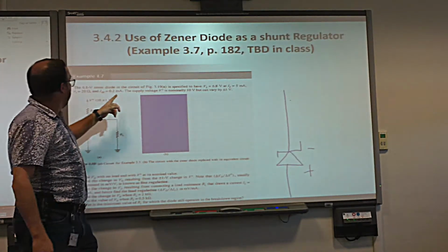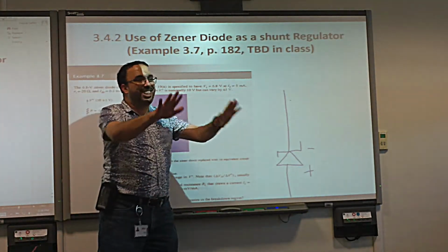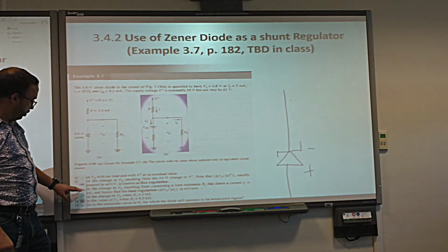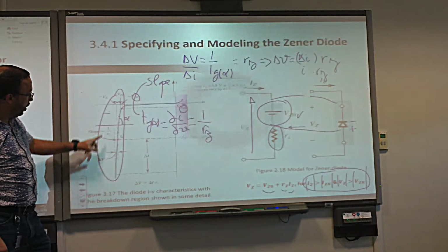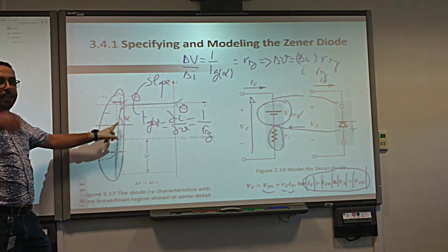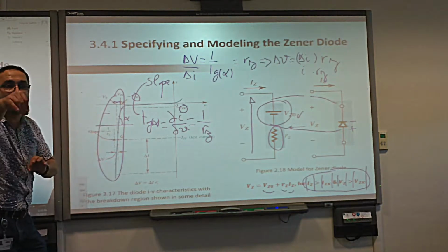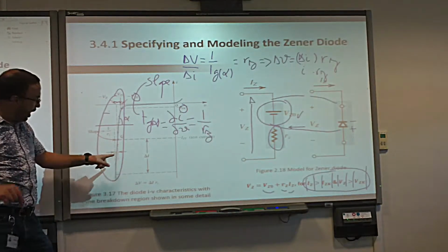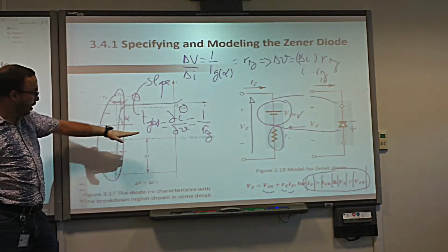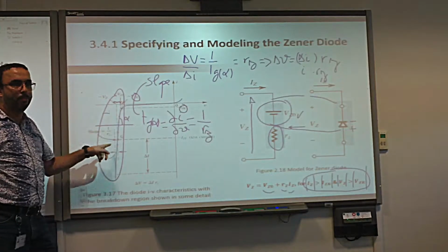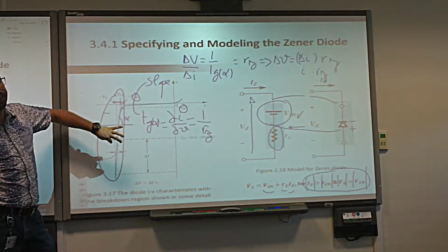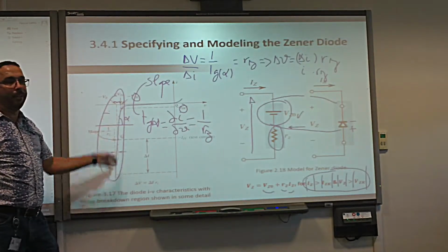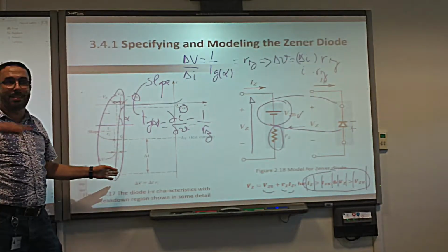دقيقة. نرجع للIZ. IZ that he is mentioning, where here is the test point. Is one point where, easy. دقيقة. Is this point. One of the points in the breakdown. He gave us only one. He said, now listen, I test this Zener diode at this particular point. يعني at this current, at this voltage. Boom. I know sure that the diode is working at this point. Do you understand? So IZ can be anywhere here. But IZK is the start.